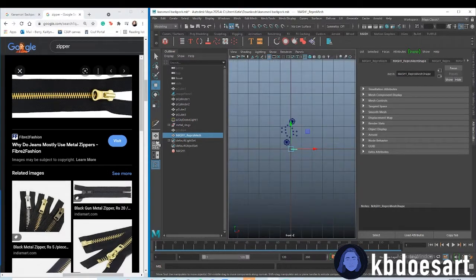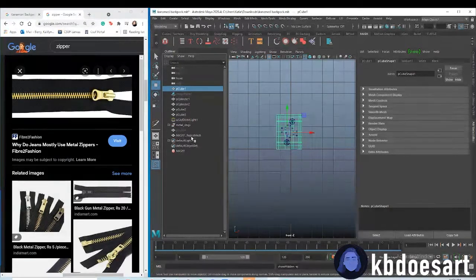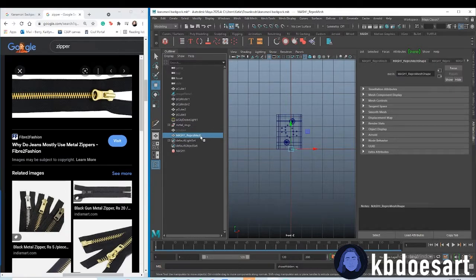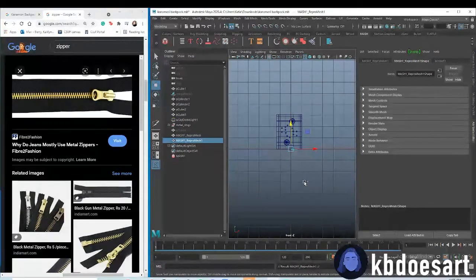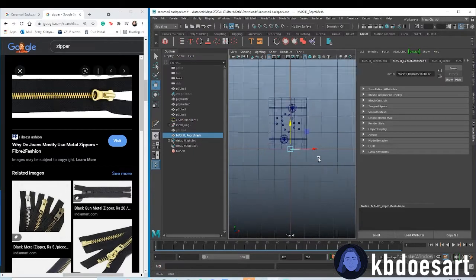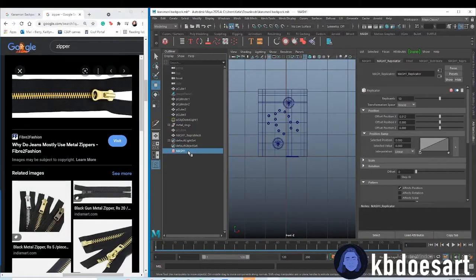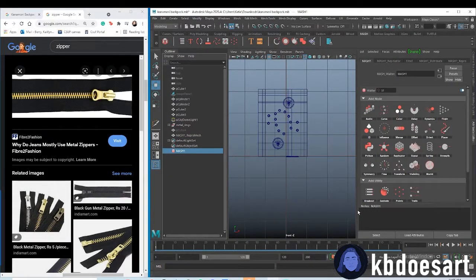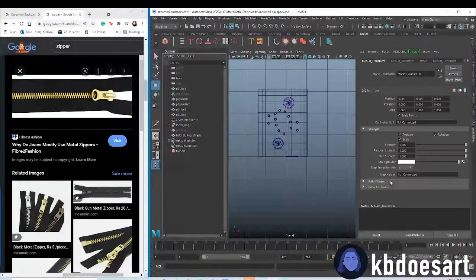So let's go into face mode. Let's unhide. So Shift H on that object, and then grab your Mesh 1 repro mesh. That's what we edited here. You can click on your mesh network, click on mesh, and then we're going to need to add a transform node.